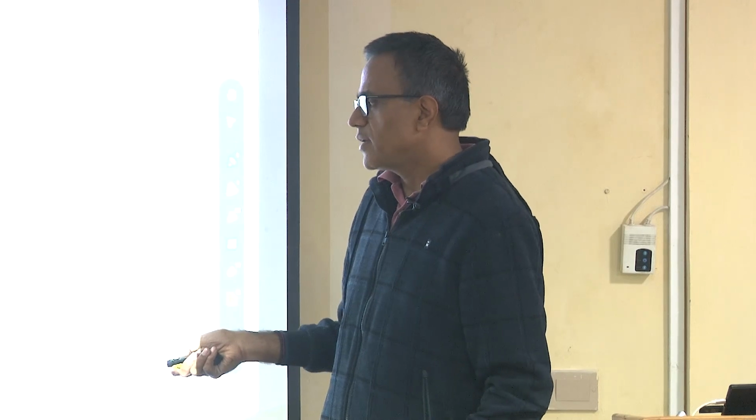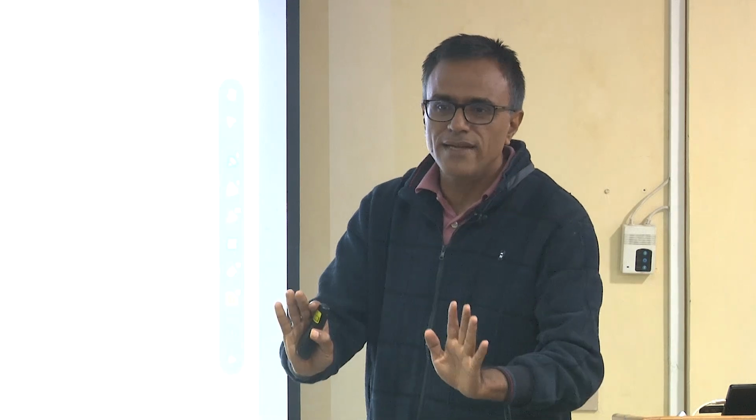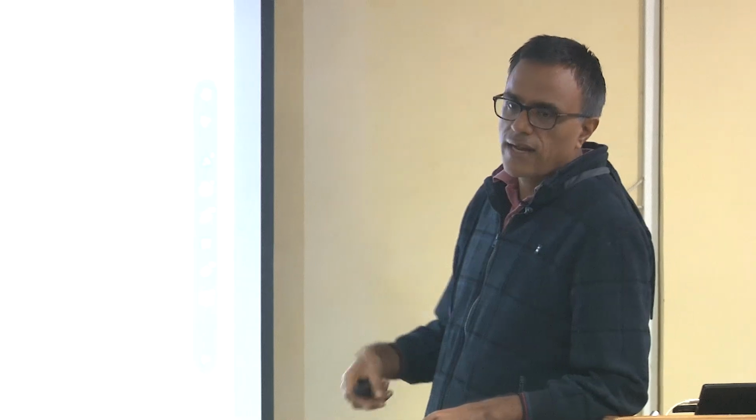Here I have mixed stream and layers, both of them are same, okay? So if the rank is 1 and the system transmits 2 layers, the second layer will get lost, correct? So what will happen is, if R1 max rate is greater than R2 max rate, essentially UE declares that the rank is 1, feeds back this precoder and the MCS accordingly.